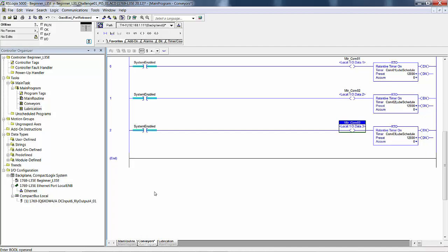Now those E's would not have been there for me because I never deleted Conveyor 3, therefore I never put logic in that had undefined tags, just to avoid any confusion here. In the current logic, the conveyor motors will run continuously anytime that the system is enabled.